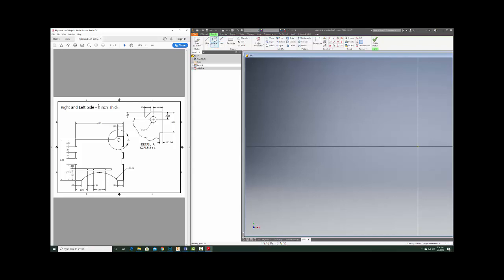So I'm going to select the line tool, and I'm going to start by drawing right here in this corner, and I'll show you why, because we'll do this arc last. And I'm just going to click and start drawing. Okay, now a couple things I do want to pay attention to. I do want to get these as I draw. Like I see that little upside down T, the perpendicular tool. I do want my lines to be perpendicular and parallel to each other, so I am paying attention to that.